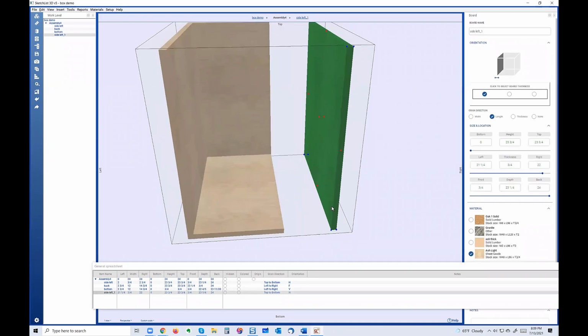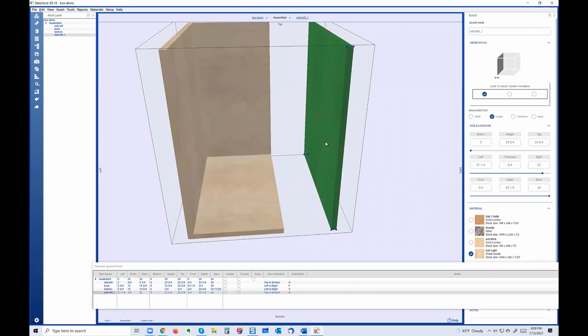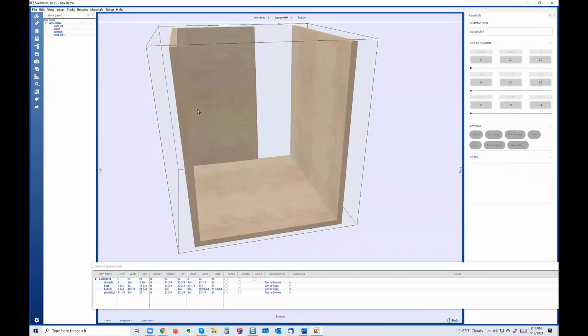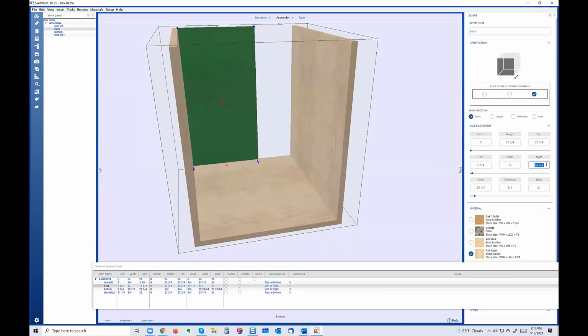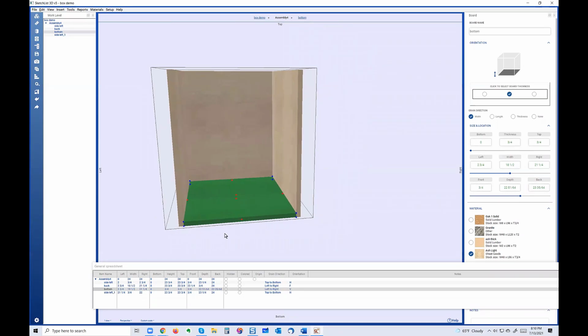And now you can use any of those tools to line up there. You want to essentially finish the sizing of these boards. So I can go here and notice that the left is 21 1/4. Actually, I think I can copy that. Come here and do a paste, Control V, and change the width like that. So that was pretty easy. And I think I can even go here and still do a paste and change the width. Now I've got those parts of my box.